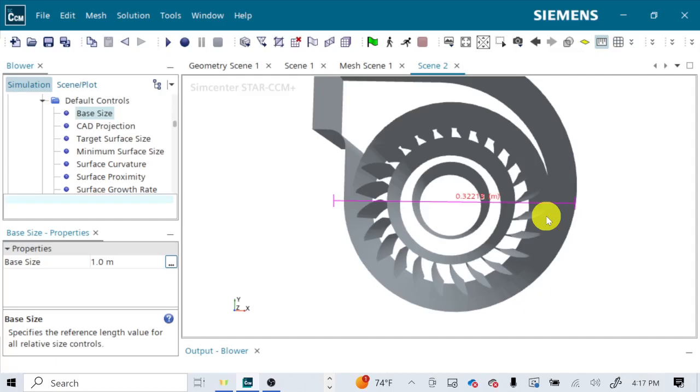A centimeter is almost certainly too big. That only gives you 30 across. That's almost certainly not enough. A millimeter is probably too small. Just keep in mind, this won't be the smallest you go. This is just your baseline. This is like the maximum cell size by default, unless you tell it something different. So a millimeter is probably too small. We're probably looking somewhere between a half centimeter to like 2 millimeters